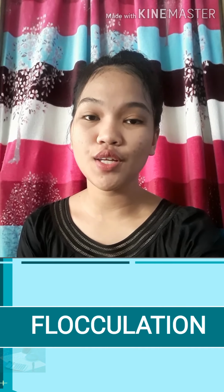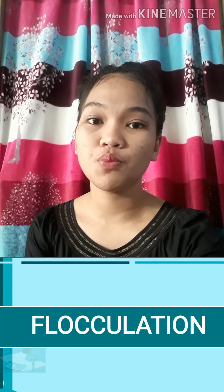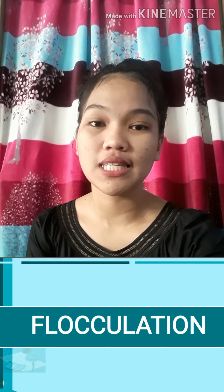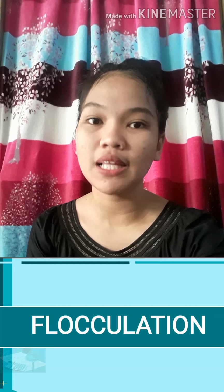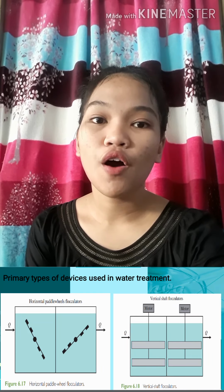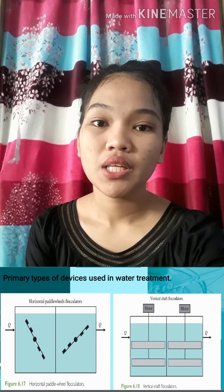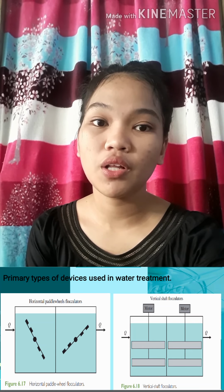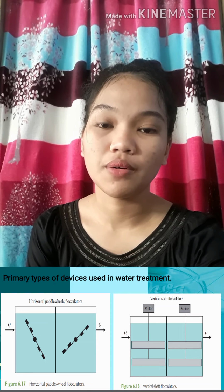Flocculation is a unit process involving the slow stirring and gentle agitation to promote agglomeration of the destabilized particles from coagulation into heavy, rapidly settling floc. So we have here primary types of devices used in water treatment. The first one is the horizontal paddle wheel flocculator, and the second one is the vertical shaft flocculator.